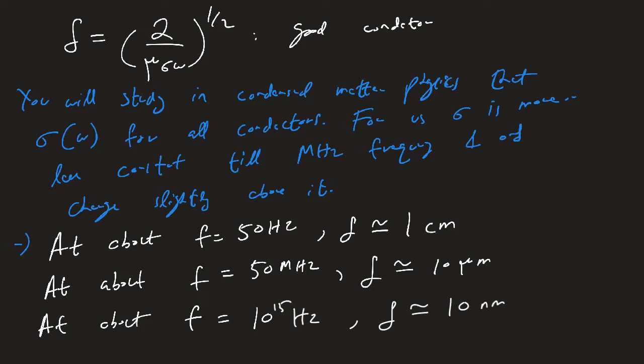So you can see that the larger the frequency, for the same conductivity, the smaller the skin depth. Of course, you'll notice that I haven't really created a linear relationship. That's because the conductivity also tends to decrease at some point as you raise the frequency. But you can look at the Drude model, but that's outside the scope of this course. So you can just take my word for it. But this is a very good rule of thumb, okay? And this expression is very useful, and it works for a good conductor.